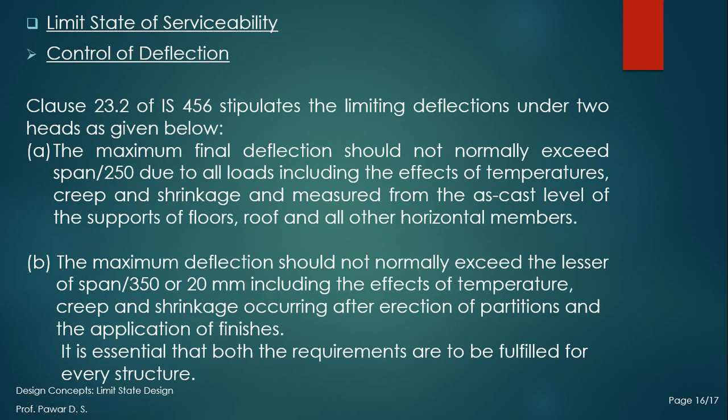So the last important thing in limit state is that we have already seen the 2 methods, the working stress method and the ultimate load method. In those, they have not taken precautions, or they have not considered the limit state of serviceability. But in the limit state method, when we increase the stresses in the material, what happens? The size of the member, or the thickness and depth of the members, is going to reduce compared to the WSM method.